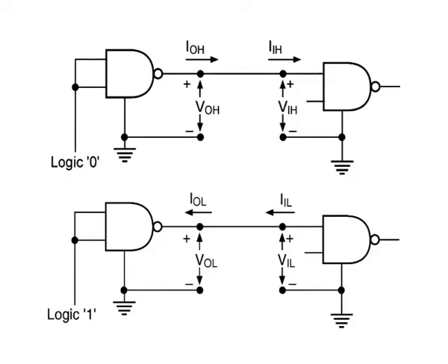Low level output voltage. This is the maximum voltage on the output pin of a logic function when the input conditions establish logic low at the output for the specified family. In the case of the standard TTL family of devices, the low level output voltage can be as high as 0.4 volt and still be treated as a legal low logic state.